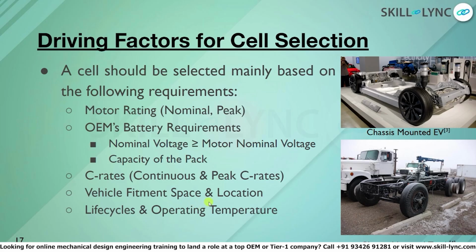And then one more important thing is vehicle fitment, space and location. High voltage battery packs in trucks, cars, etc. can be mounted on the chassis, on the rooftops, or anywhere. Knowing where that location is, and how the battery pack is going to be mounted, is very important, because that will give you an idea of what the vibration loads would be, and what kind of environment it's going to be, like too much heat.